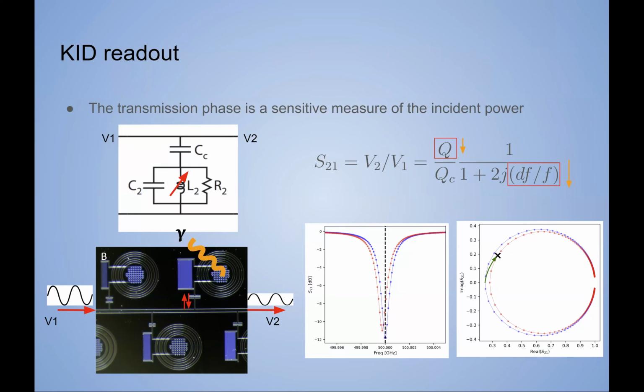Wait, so then how? You have a mixer in there. You have sums of sinusoids. Yeah, there are intermodulation products that you eventually have to care about. Depending on how far apart your resonances are, would your third order intermodulation mess with your phase measurement, right? I think it kind of just becomes a noise floor, because there are so many of them.